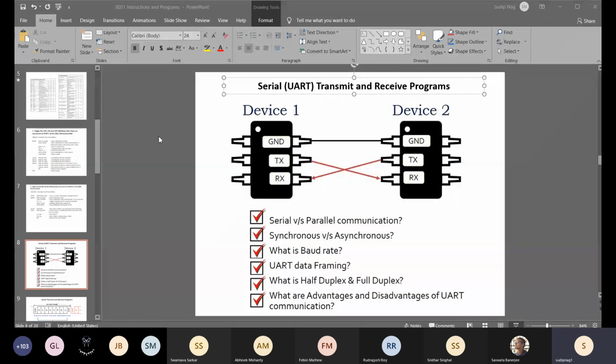Now, if you look at this, there is a start bit information. The x-axis is time here, and the y-axis is logic level. This is logic 0, this is logic 1, and this is time t equal to 0 and onwards, with certain unit time instances. Each double-headed arrow indicates one bit time.